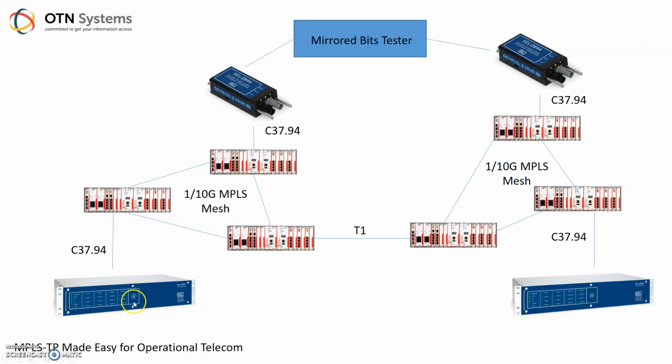So I'll be injecting transfer trips into this DTT Schweitzer module, and they'll be sent across one channel over a T1, and then back into another XTran network down here into the remote DTT module. And the C37 converters there are going to have another separate channel over the T1, and this one is going to be connected to a mirrored bit tester, and I'll be able to look at the latency in both directions, injecting traffic in both directions, measuring asymmetrical delay, measuring packet loss, and so on.